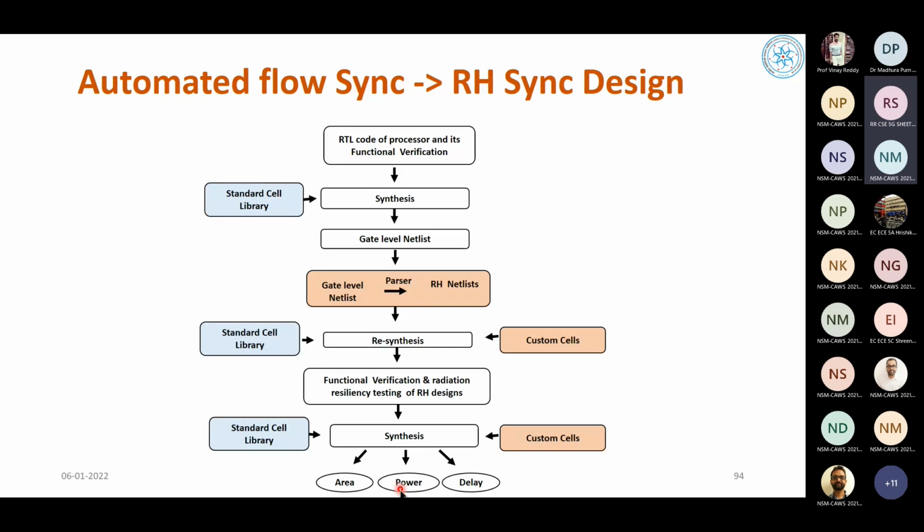Once you give the test inputs, the entire circuit will respond to it, and then what you get is the final output, whatever add, load, store, or whatever instruction you're executing. When you do this, all the internal nodes also switch. This tool generates what is called a VCD file, value change dump file, which tells you which internal gates are switching.